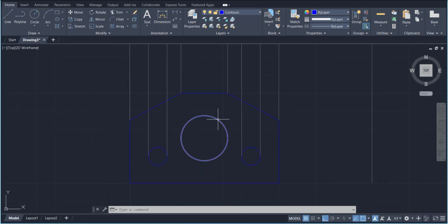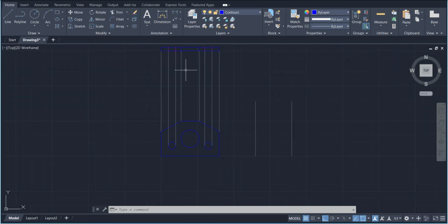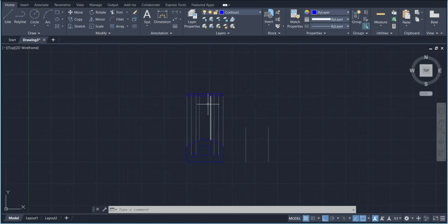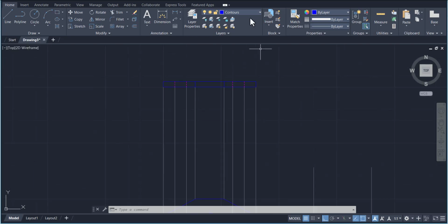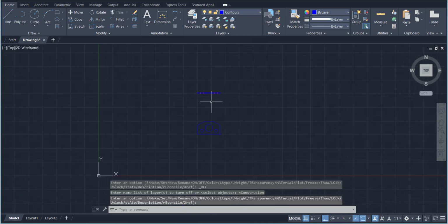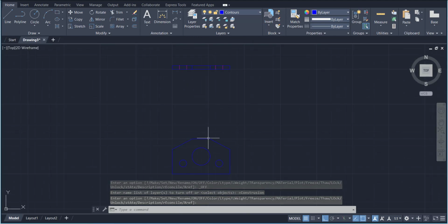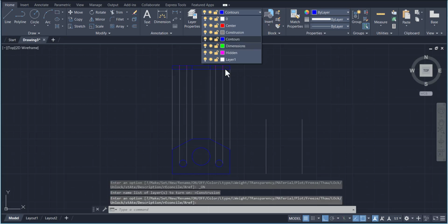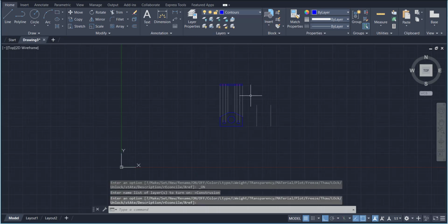And the hidden line for this circle will not be shown because this point and this tangent or this quadrant will be on the same line. And whenever we have a hidden line and a visible line, then the visible line will dominate. So that's why we don't have a hidden line here. So we can also hide these construction lines if we want, because these are only for construction. It's helping us transfer our view from one view to another view. But we needed that from this side.